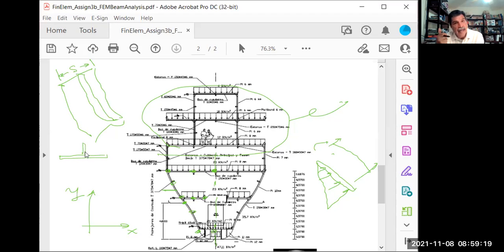And then you can calculate area. Remember, that's something that we said we need, and inertia. In that case, it's a good idea if you also include the sectional modulus. So after you calculate the bending moment, you can finally calculate stress.